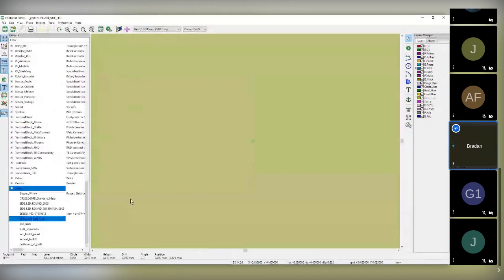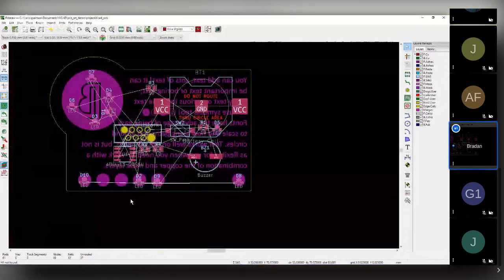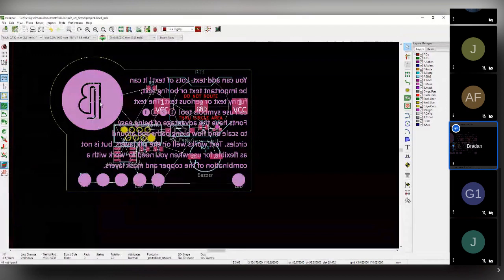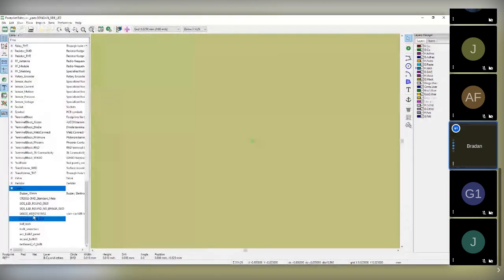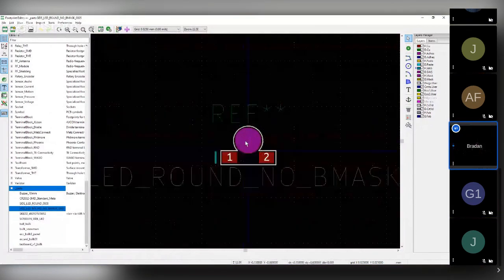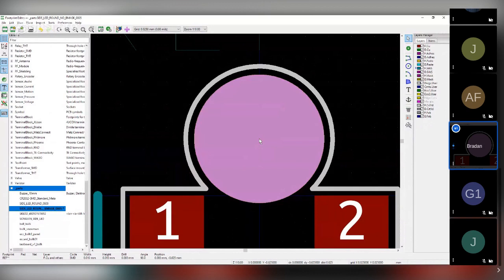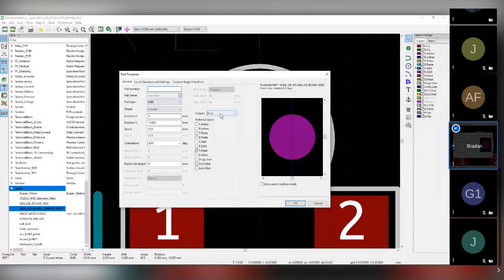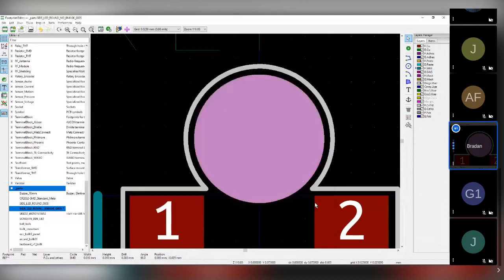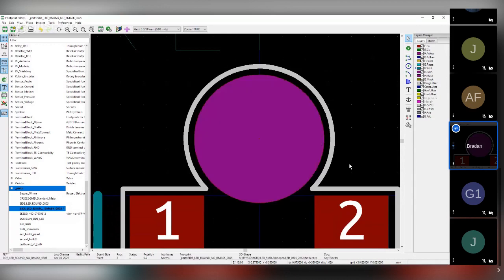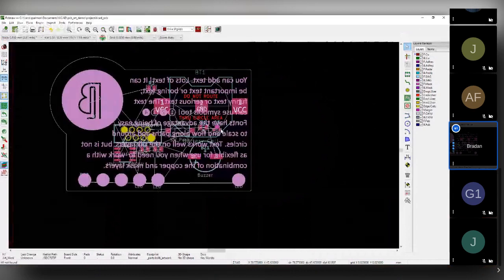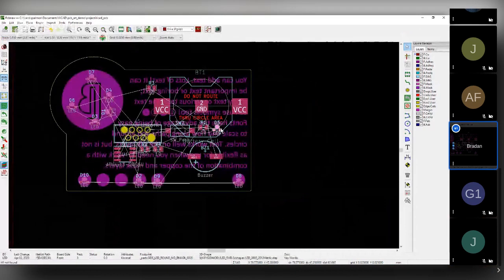But if you want to do, as in this example, some very interesting shape that's got some coloring in it, I created another version of that, which only has half of that whole process. It has the same trick, but now it's only on the front side copper, and it assumes your artwork will remove the mask and the copper from the back side. That's how I ended up creating that little LED that you see right here, which is this one right here.